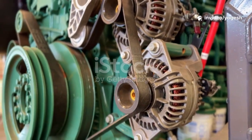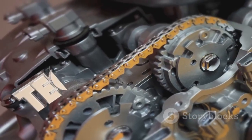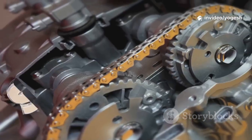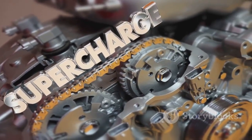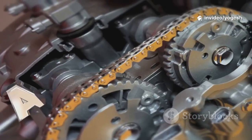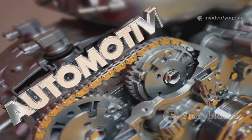Let's walk through a real-world example by building a motorized rock tumbler. This project will use a combination of springs, belts, and chains to create a smooth, reliable motion. Imagine the process from start to finish as we bring together mechanical components to form a working system. The first step is to draw the main frame, the motor, pulleys, sprockets, and the barrel where the rocks will tumble. Each part must be carefully positioned to ensure everything fits together seamlessly.